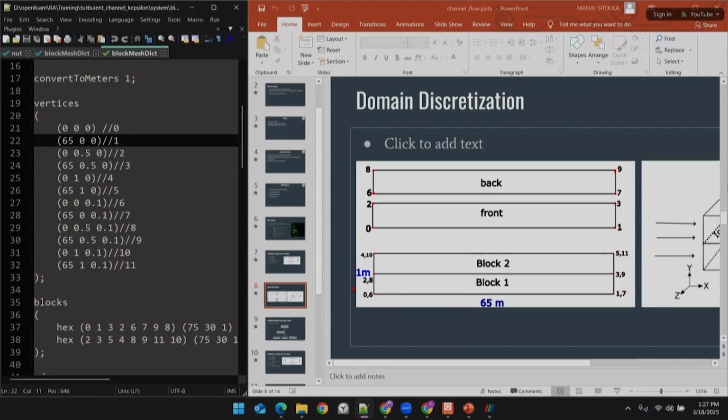So similarly, after we complete the front plane, 0 1 2 3 4 5, we move on to the back plane coordinates, that is, number 6 coordinate. You can see that we are now moving z to 0.1, because we are doing the back plane. So it would be the same as 0 1 2 3 4 5, but we just keep z as 0.1. These are the same coordinates but in the back plane. We just change the z coordinates to incorporate this effect without changing the x and y coordinates. I think you understood how these coordinates are formed and how blocks are created.